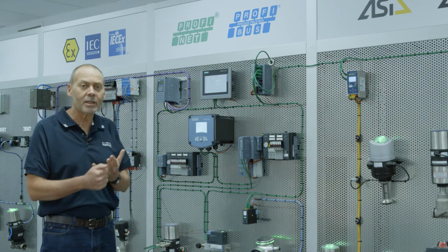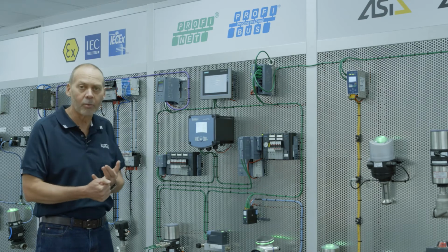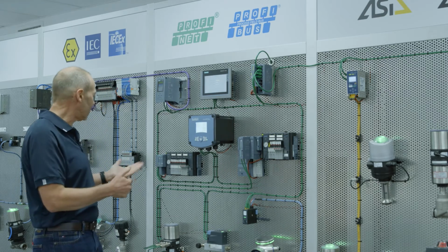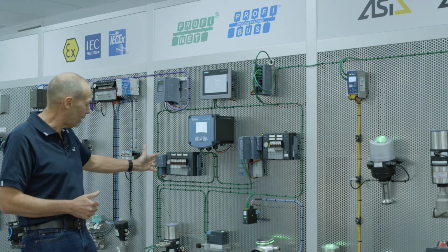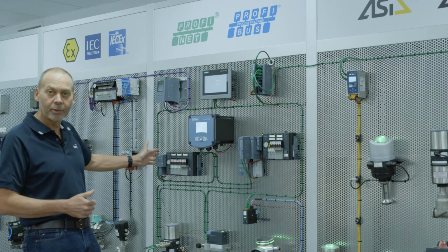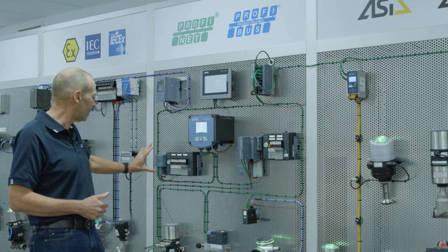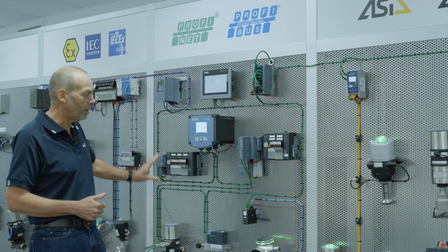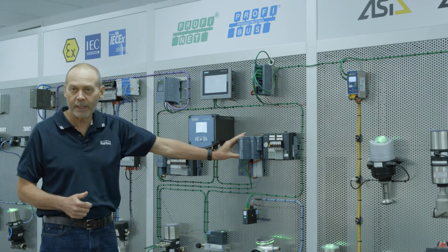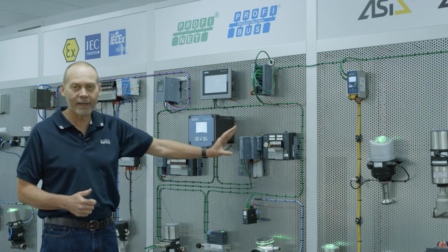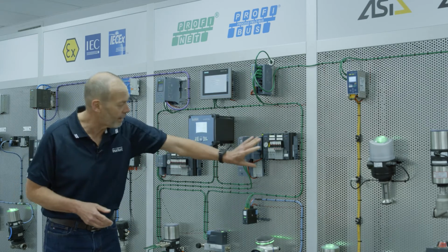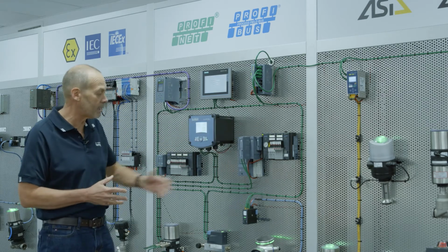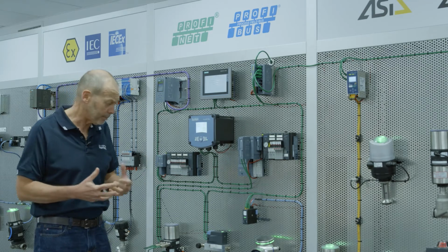The second way is to use distributed I/O blocks. To show you an example of that, we've got our integration here with the Siemens ET200 SP, where we've got inputs, outputs, and valves all connected on a single node, and also the ET200 SP HA, which is the high availability version of that system, where we also have inputs, outputs, and valves all connected into an I/O cluster.